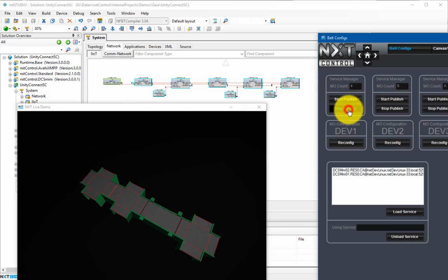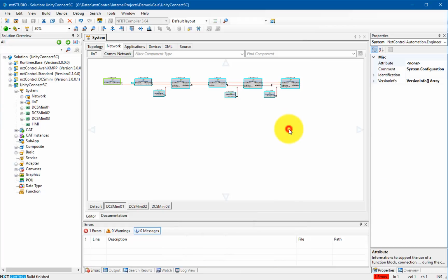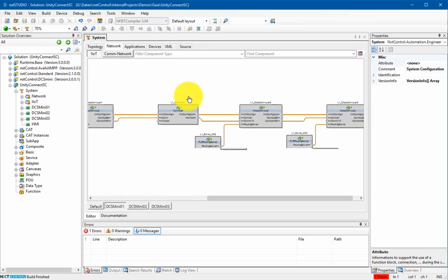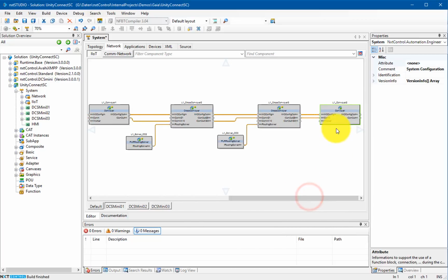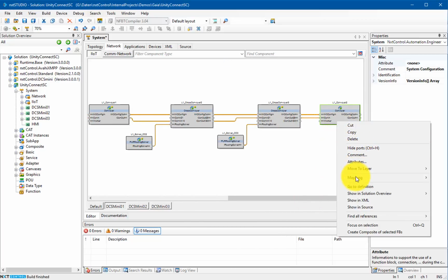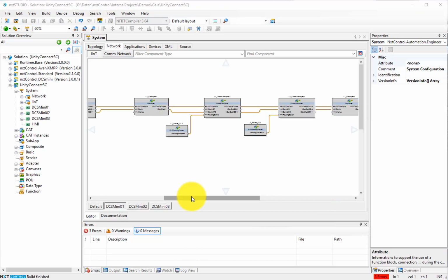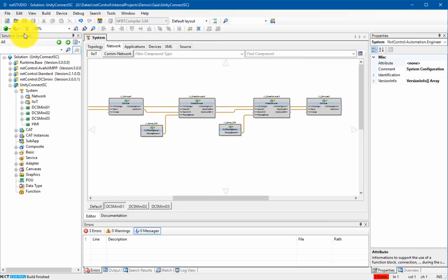To extend the application, we go back into the application environment of the studio. Now we simply duplicate a conveyor object and wire it to the application. After that, we assign it to a controller and deploy the controller again, so that all our modifications are recognized by the controller and the application is updated with our new object. To do that, we simply start the deploy command of NXT Studio and update our controller with the new application.